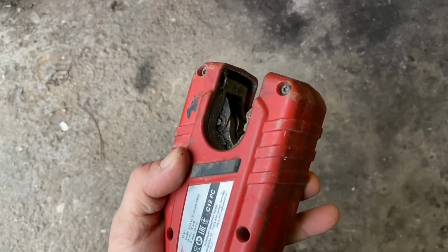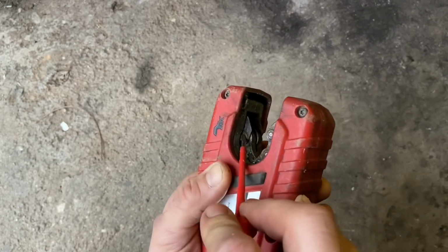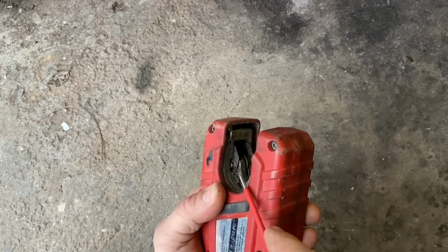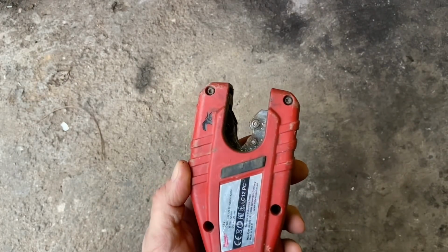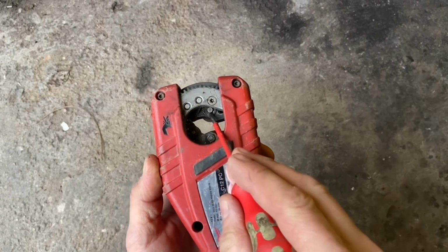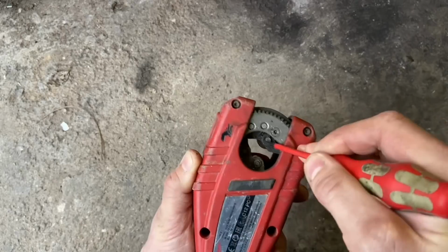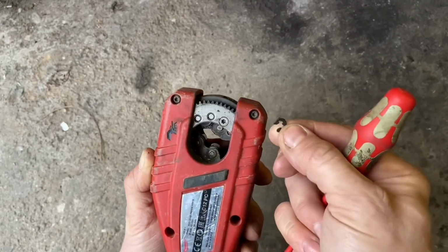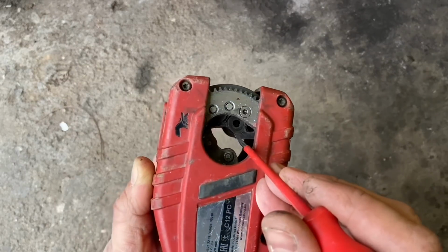You see, just there, got a little circlip. So I'm going to ping that off and try not to lose it. Let me just move it slightly. There, that's better. See that circlip there? I'm just going to ping that out. Right, there we go. Literally landed up there. Okay, and then all you do is push this pin, pop it back up.